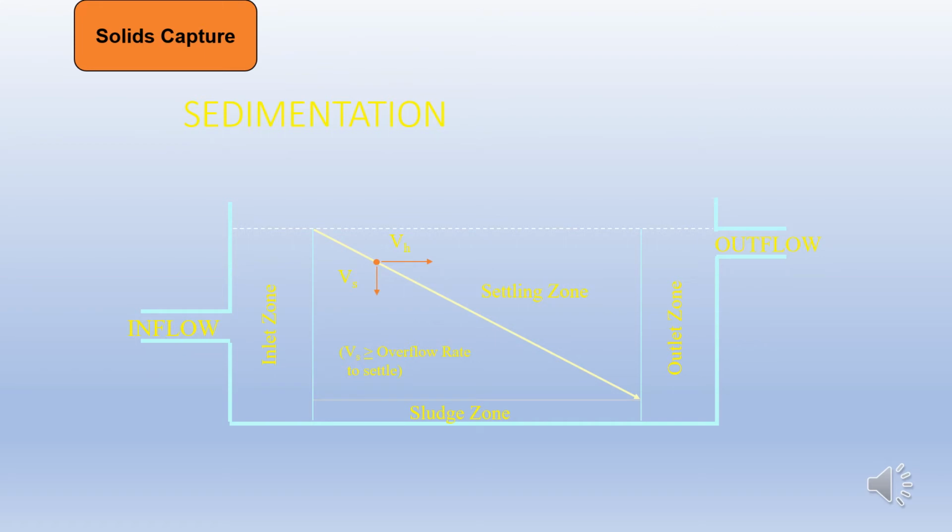You can see here a pretty simple design, something that's called a settling basin. This is one of the easiest, most low-tech ideas when it comes to allowing solids to be removed from your system. The next slide actually shows a picture of what one looks like when it's functioning. Basically, you slow the water down, make it work against gravity, and then fall out of solution. The optimal design would let clear water, or at least fairly clear water, go through the outflow. That helps your filtration units later on down the line.